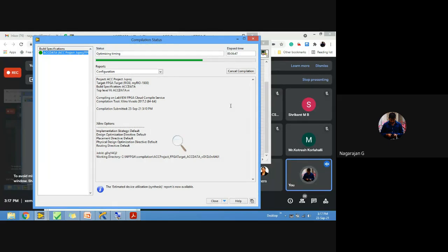We have used FIFO write right now. We have not used FIFO read. When we use FIFO write, we are going to put the data into the target FIFO. So we have to configure the FIFO method: right-click, select method, and go for write. When we go for FIFO in, we have to specify the FIFO. If we leave the FIFO unwired, it is going to give a broken wire, and likewise if we do not provide the timeout values.